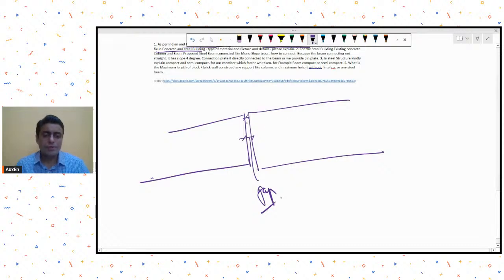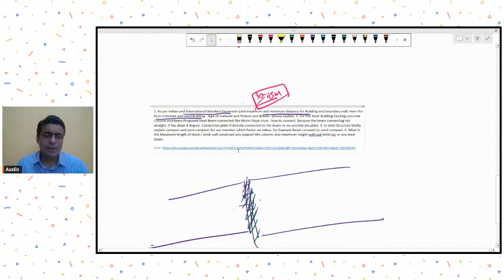The type of material. So once you leave this gap, then you fill it up, because otherwise if you leave a very large gap, this space may not remain serviceable. So you will have to leave this gap over here, and then because you want to have it serviceable also, you will fill it up with some non-shrink compound. Some people fill some silicon based product over here, or any other non-shrink compound that you wish to fill over here, or any rubber or elastomeric compound is also filled by people. So that is what they do.